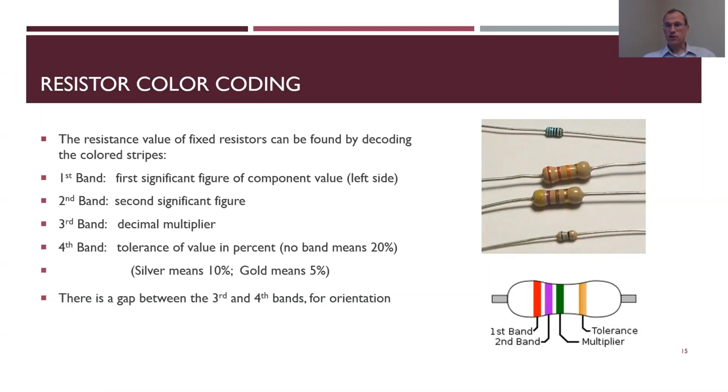But again, they look very similar. So how do you know exactly what the resistance of these guys is? The way you do that is with all these little color bands, all these little stripes. Those stripes essentially tell you what the resistance is. In general, there are 4 bands. These metal film ones sometimes have 5 bands. Sometimes you only see 3 bands on them. We'll get to those differences in a minute, but generally 4 bands is what we'll see.